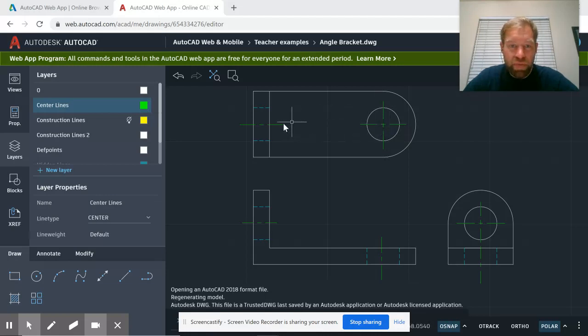And then over here represents a circle, and it's a crosshair, but you can't see the other crosshair because you're looking at it just from a top perspective. So you wouldn't see the other side of the crosshair. But this just lets you know the circle goes all the way through the surface of that piece right there. Then down here, it shows again the same thing. And if you translate these lines down here, it shows the hole going through there again.